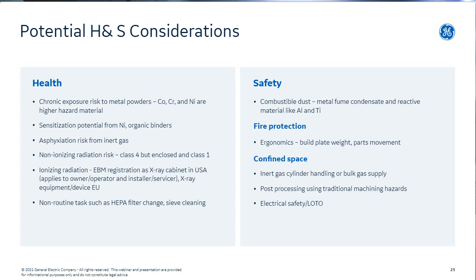From the non-health side, the safety consideration should be really around all the combustible dusts, and also the consequences that can be created out of that, like fires or explosions. And there are other hazards like confined space or even working from heights. It depends on whether you need to go inside the machine and it's very tight and close, or if you need to go outside of a machine, then it can also be a specific hazard and risk that needs to be considered.